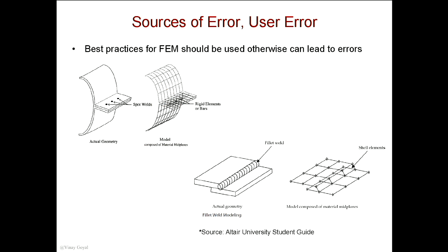Other things to point out, so these, for example, a joint, a clamp, and these are connected by spot welds. You can represent the spot welds with rigid elements, typically, and then these two structures look like shells or plates, so you can represent them using the mid-surface of these plates. So that would be a good way of doing it.